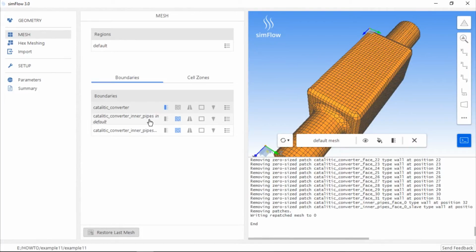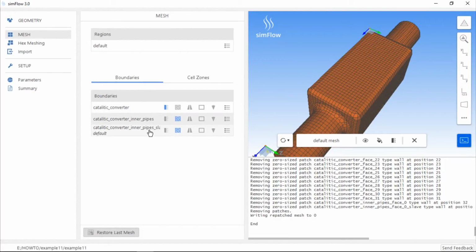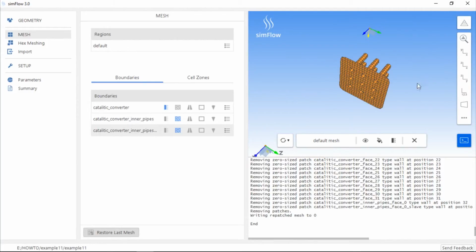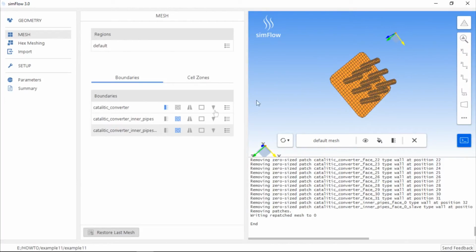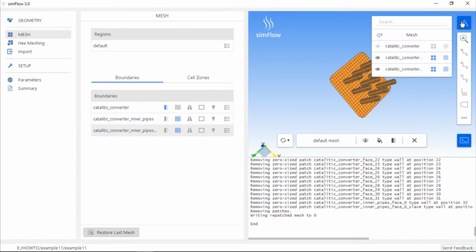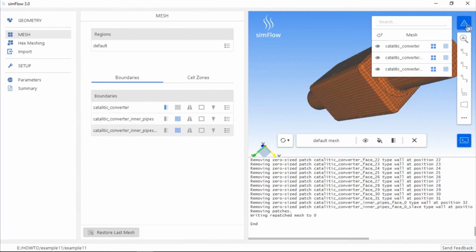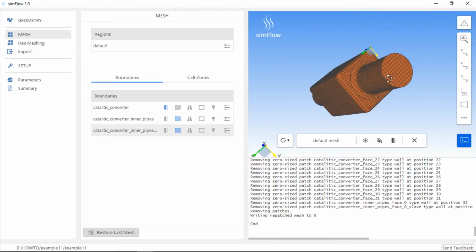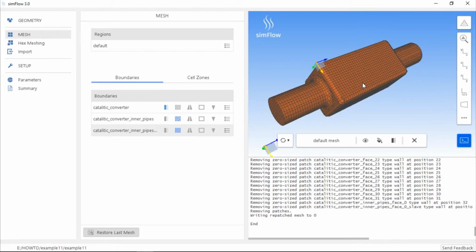By creating a baffle, we simply created two exactly the same boundaries, with faces and nodes located at the same positions in space. So, the mesh is now on both sides of the geometry, and if we assign wall boundary condition to these baffle boundaries, we will be able to simulate flow on both sides of the plate and small pipes. This approach gives us the possibility to simplify the geometry and simulate it as an infinitely thin wall, and also allows us to use a coarser mesh.